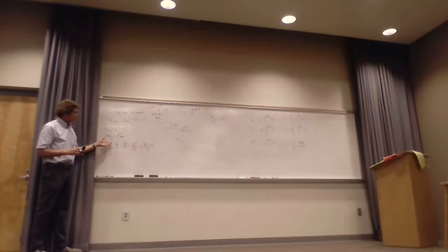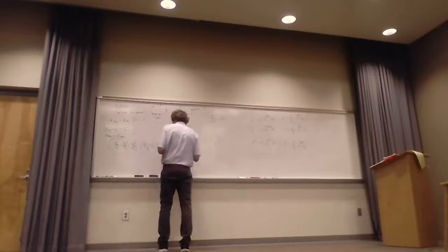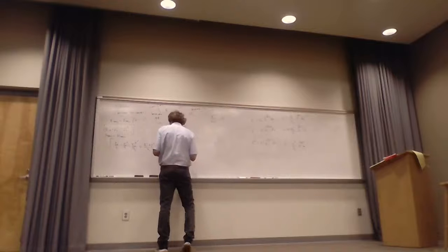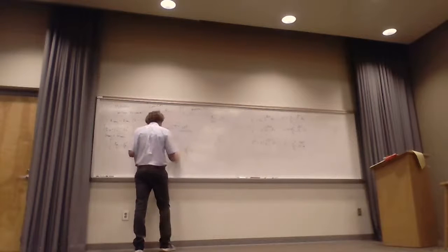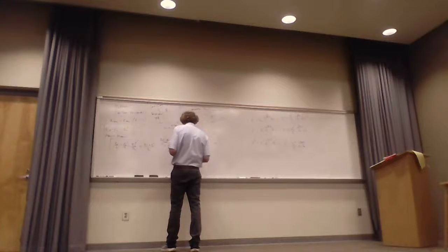Now I can go ahead and divide both sides by E naught incident. If I do that, I get 1 over eta 1 plus, and here I define what I've been waiting to do, the reflection coefficient. It is symbolized by gamma, and it's E naught reflected over E naught incident. It's a ratio of the reflected to the incident field's magnitude. So that becomes the reflection coefficient